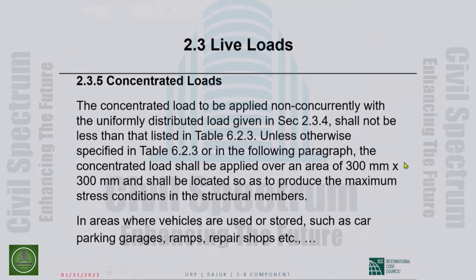Here maybe I should point this out: unless otherwise specified, the concentrated load shall be applied over an area of 300 millimeters by 300 millimeters. That is important, and it shall be located so as to produce the maximum stress conditions in the structural members.